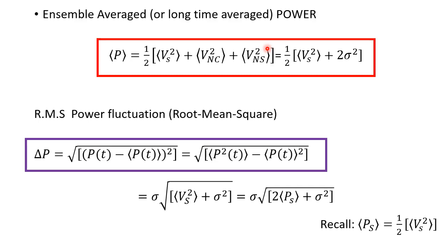You see that that first moment will give me 0. So that term really doesn't contribute, and you have only the square terms contributing to the average power. My average power turns out to be, you know that the second moments of VNC square and VNS square both give me sigma squares, and hence this is twice sigma square here, and this is the average power that I have.